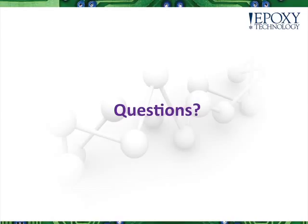Can I use my own radiometer or do I have to use one from the lamp manufacturer? Well, your radiometer is probably going to give you solid overall results in terms of your intensity, but it's best to use the one from the lamp manufacturer. The thing is the output spectrum that it covers. Some radiometers are not designed for a really wide range of lamp outputs, and you really want to make sure that the radiometer you have is going to actually measure the intensity of the lamp output.